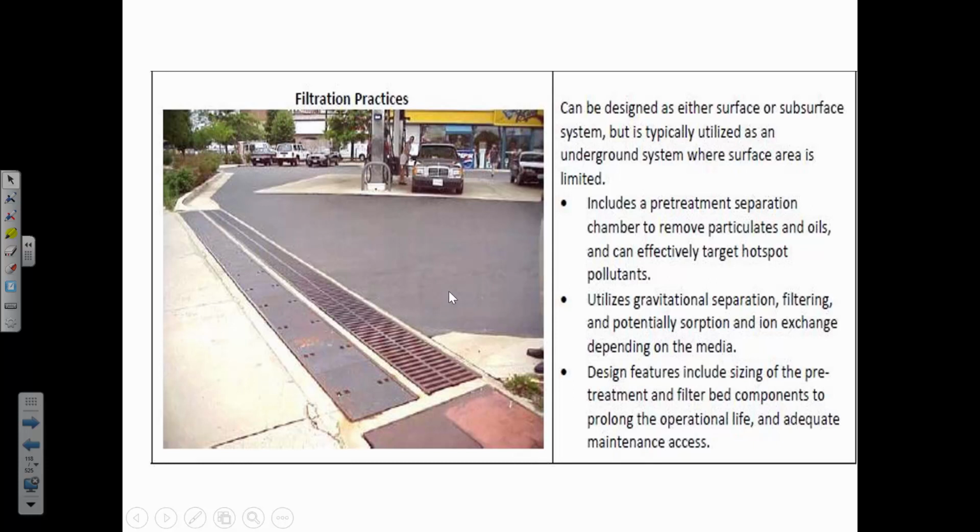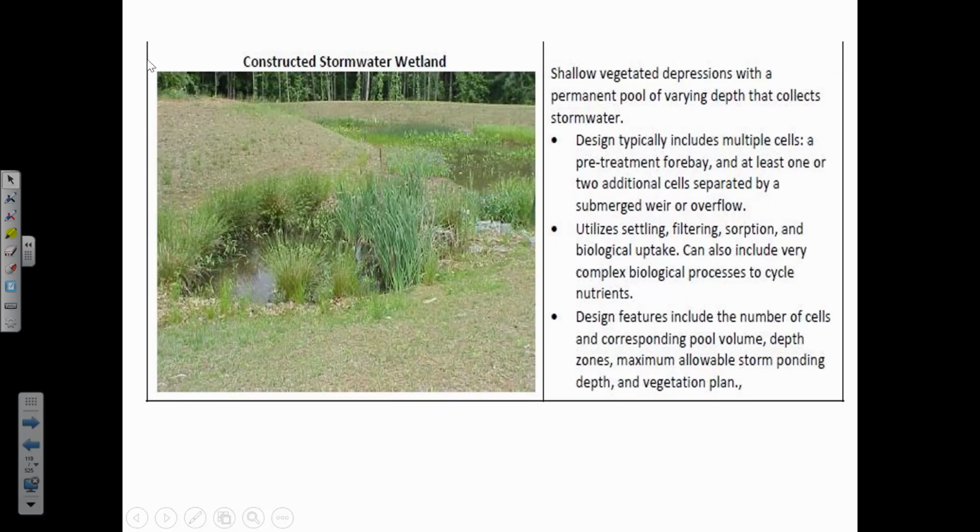What you might do is collect the water from the surface runoff from this filling station and then have it go to an open grassy pond area, and then the organic pollutants could evaporate, any kind of sediment could settle, and then any leftover water that didn't evaporate could be channeled somewhere else after it's been pre-filtered a little bit.